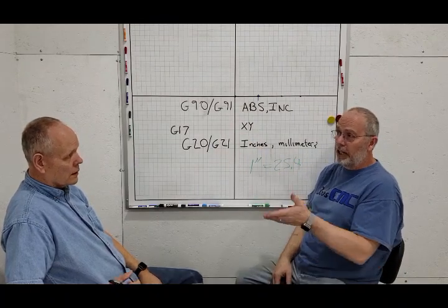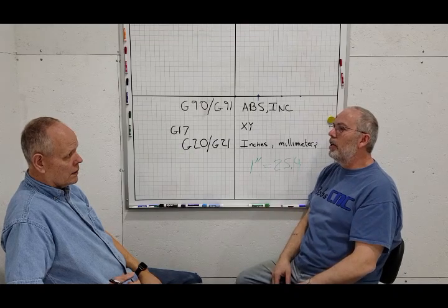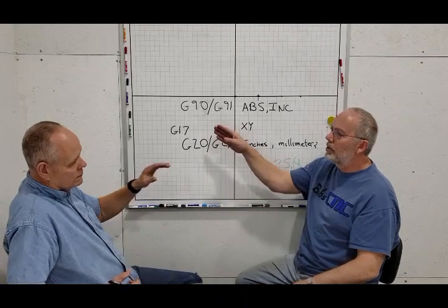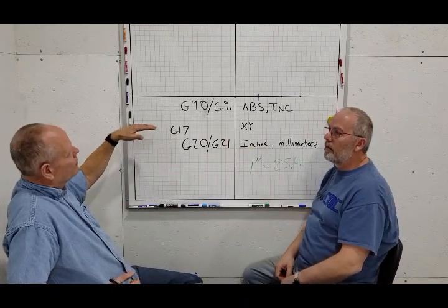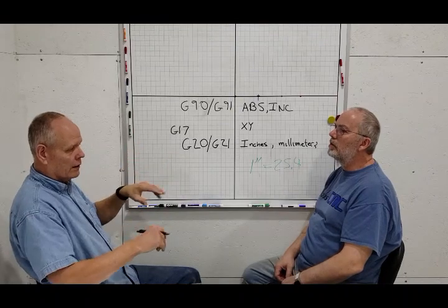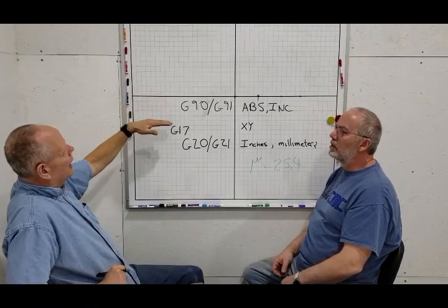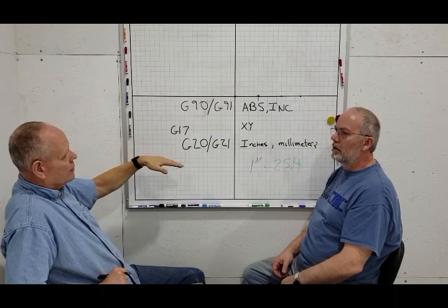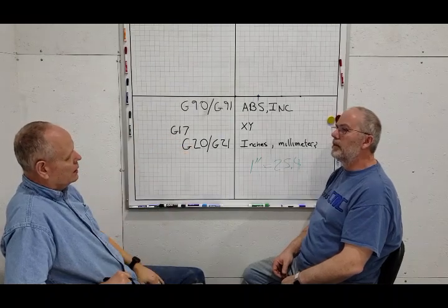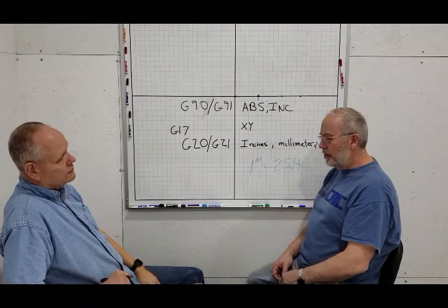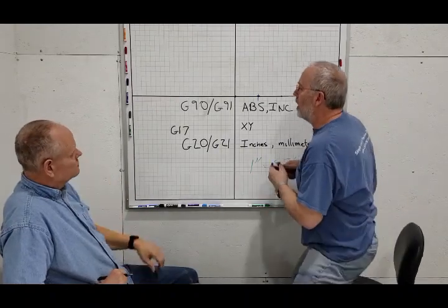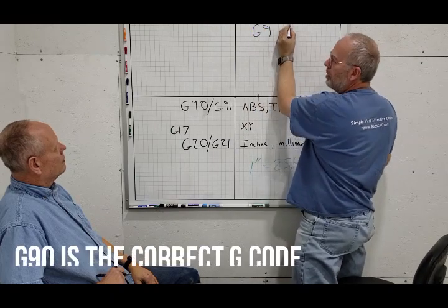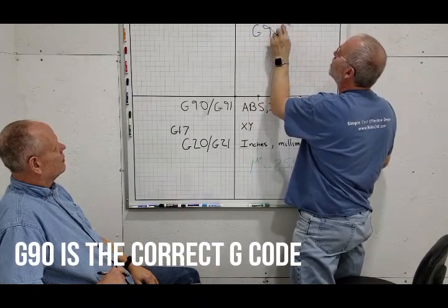And I would also suggest if you're writing a G-code by hand, you can put certain symbols so that you can write comments after it. So if I'm typing in a text editor, I would just put G90, return, G17, return, G20, return. Absolutely. And if you wanted your reader to be able to understand, you would say G90, and then I can't remember what it is, I think it's brackets.